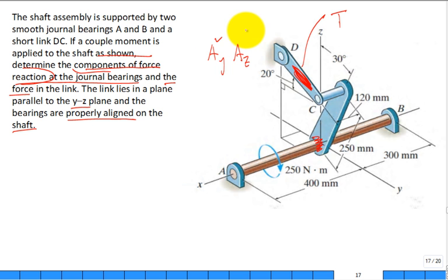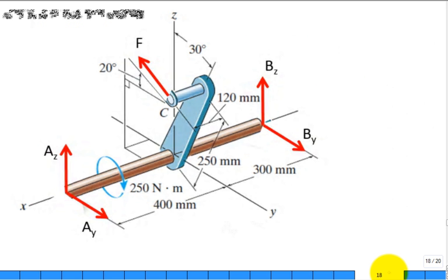But I have two components of the reaction force at A. Likewise, I come out to B, I would have 2 components. True? So I cut, go circle, cut, come up here, cut, like that, and then come down, and I generate a free body diagram. And I try to clean it up, and I try to put my reaction supports in there.